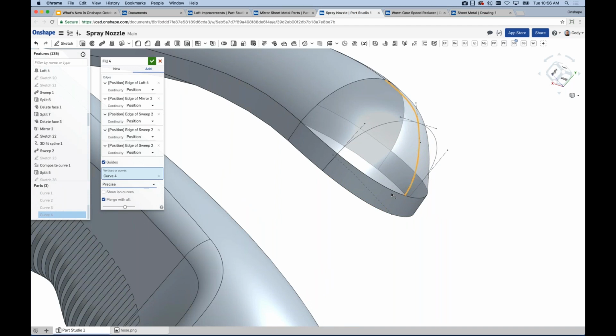However, if you've done a lot of this, you'll know that if you're going to use a guide like this, you have to have very clear rules for the curve. The curve needs to start and end at the exact points where your fill starts and ends, attached to the entities that you're referencing for your fill. So there have always been very strict rules for how curves should work if you want to use them for a loft in the past.